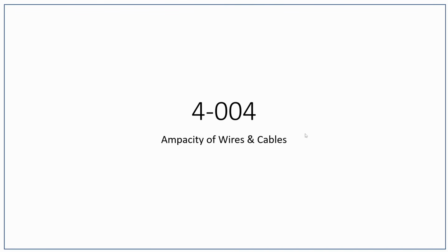All right, guys, let's do this. 4004, probably one of the most important code rules. This is for determining the maximum ampacity of wires and cables.